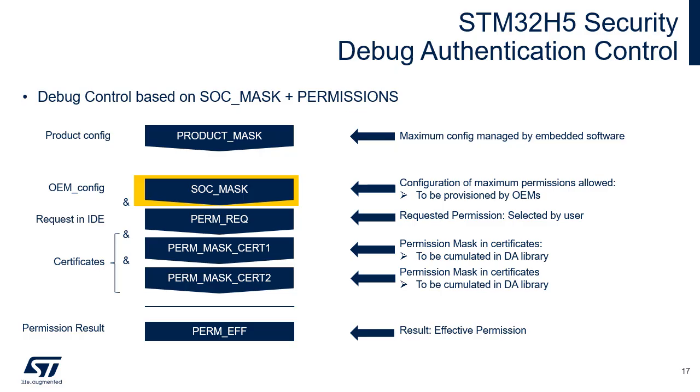For fine-grained access control, the PSA DAC specification defines a standard mechanism to associate certificates in the chain with a bitmap of logical permissions. The debug host requests access to a set of permissions via the authentication token. The effective permissions are computed by masking requested permissions with permission-limiting constraints from the certificate chain. This mechanism allows certification authorities to restrict permissions of issued certificates. Transition from closed to open or TZ closed states is a matter of correct product configuration and provisioning.